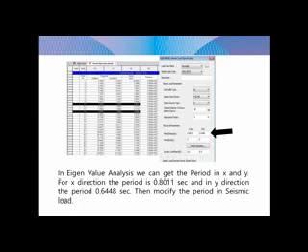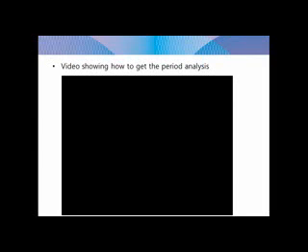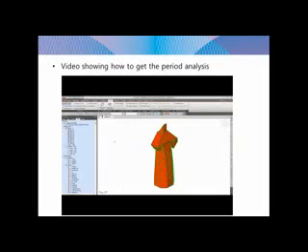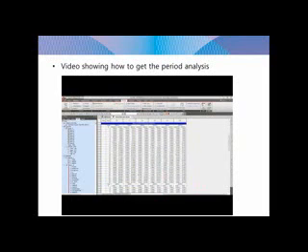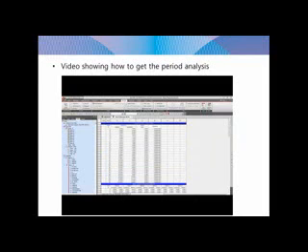After running, so you can get the result, go to the results table, vibration mode shape, and look for the mass participation of X and Y. So X is mode 10. Let me see. Yeah. And then same with the Y. So the period is mode 8 and mode 11. Okay.